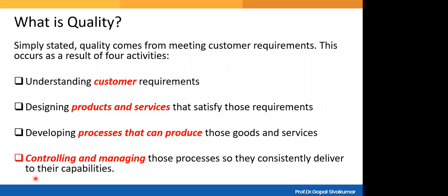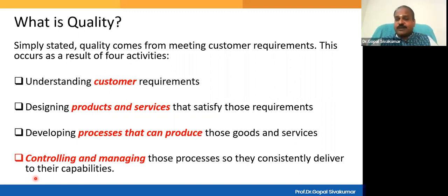You can't. No. That's where, if you don't want to stand there throughout and don't want to check very frequently, that is why you are shifting your focus from 100% inspection to sampling. Am I right? 100% inspection to sampling. You will only check few pieces at some planned frequency. Maybe once in a shift or twice in a shift, it varies.